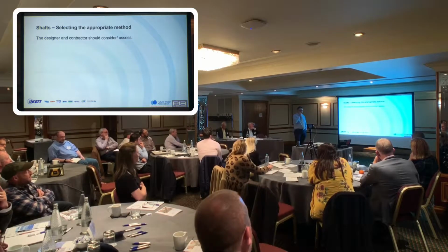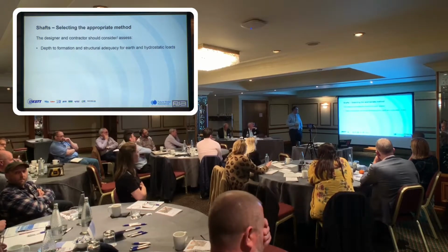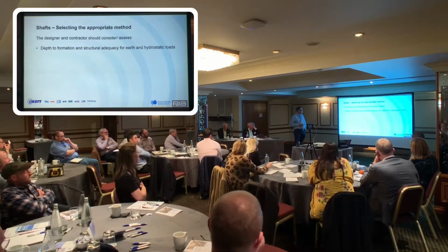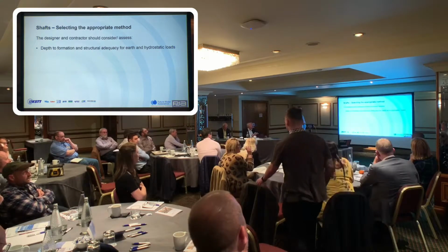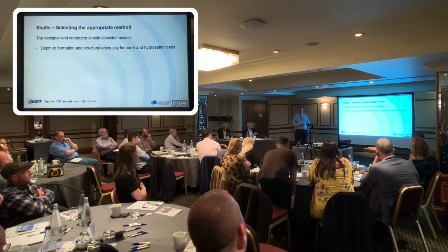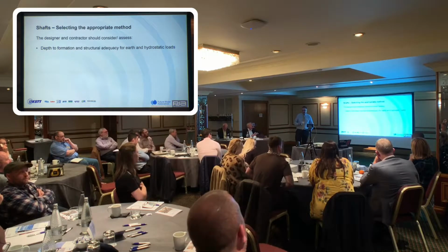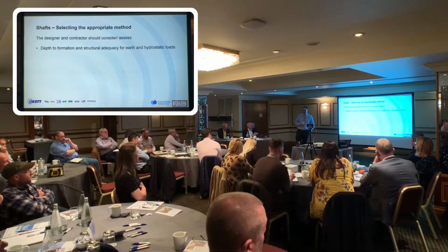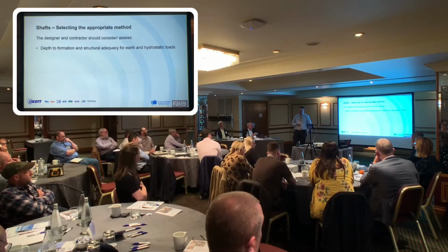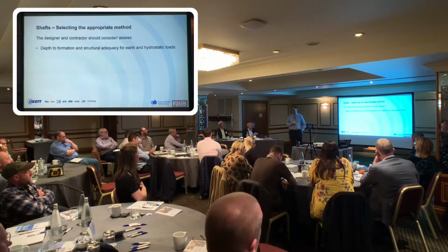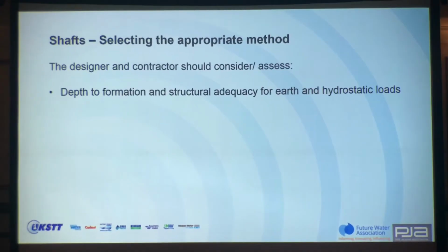So I've picked out a few points from the different methods. When you're looking at your shafts, the thought should always be what the depth of formation is, and then the adequacy of that system for earth and static earth pressures. So, for example, if I take an extreme, clearly, if you were trying to put in a shaft to 35, 40 metres, it'd be somewhat of a challenge to put a sheet pile cofferdam down it. You'd probably find that by the time you were past 15, 20 metres, you were going to be starting to struggle with frames at such close centres it'd almost be like fully closing a heading.